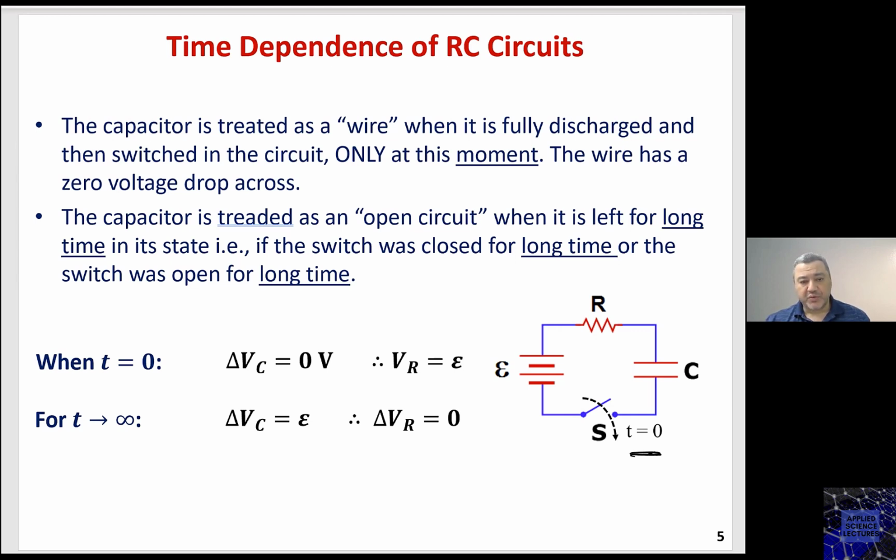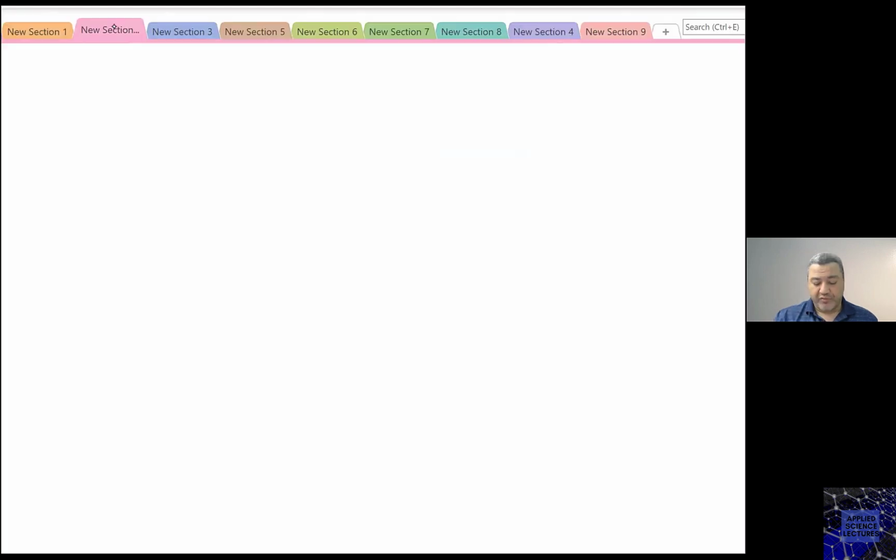Right at the moment when I close the switch, when the capacitor had zero charges in it, right at this moment, only that moment, I can replace the capacitor with a piece of wire.